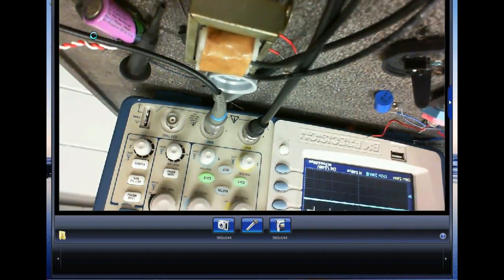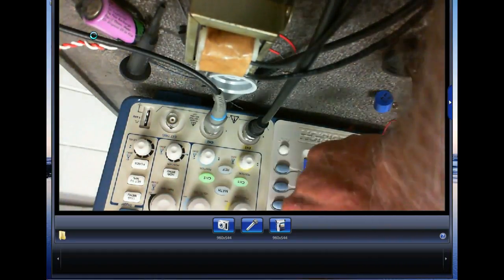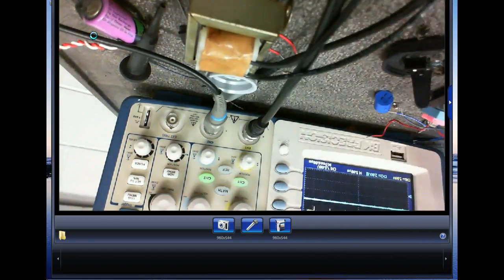So it would be like me taking a switch and doing one. Turn off, turn on, turn off, turn on, turn off, turn on. And the switch don't get hot at all. Now these guys are going to get warm because they are not switches, they are transistors, so they will always drop voltage. They just don't drop very much. So we'll still have to heat sink them and stuff like that. So what I'm doing is I'm using this to simulate the output of my oscillator. It puts out what we call a square waveform.